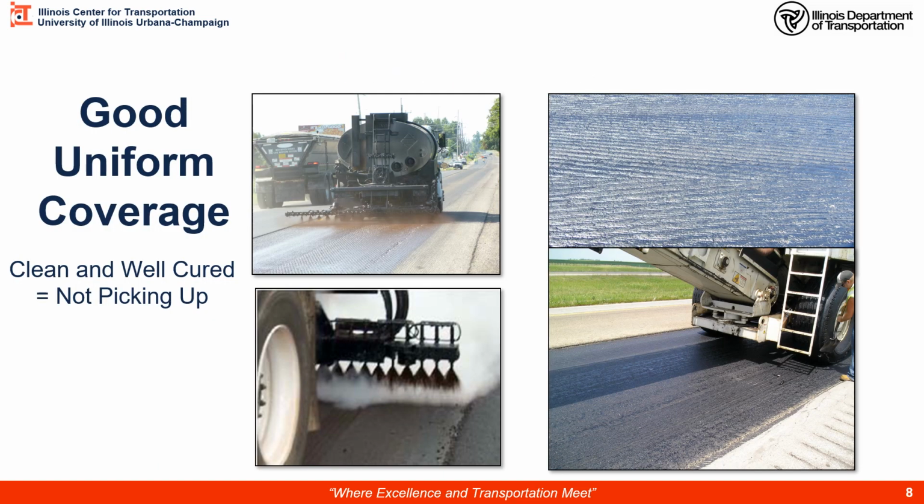Here's some examples of good uniform coverage where the equipment has been properly prepared. We have the right nozzles in place. We have overlap of the fans. And what I mean by fans is the spray overlaps. Gives us a nice uniform coverage.